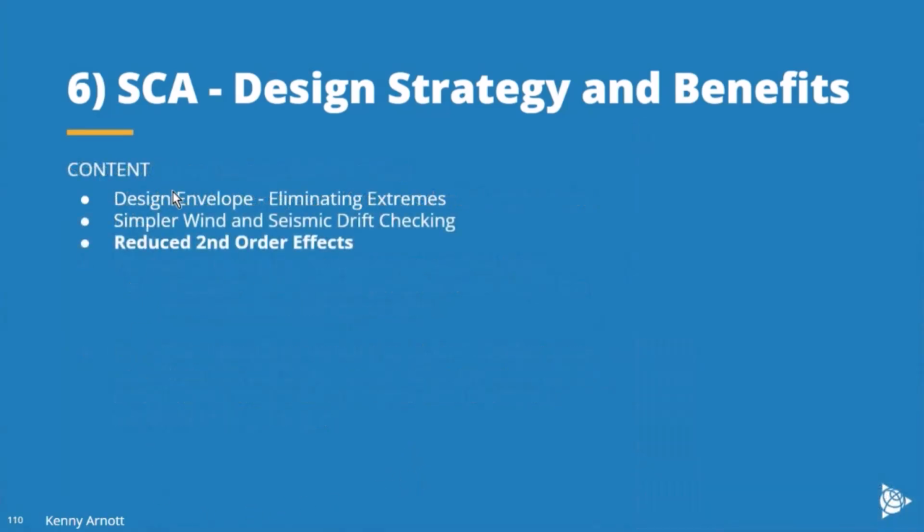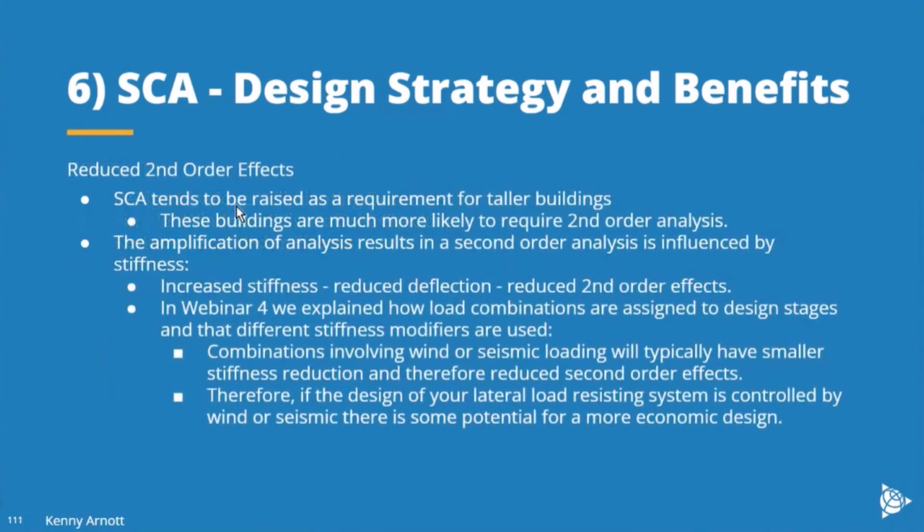And then the final part in here about the benefits is a potential for reduced second order effects. Stage construction analysis tends to be raised as a requirement for the taller buildings, and these buildings are more likely to be susceptible to significant second order effects. The amplification of analysis results is influenced by the stiffness. As you increase the stiffness, you reduce the deflection, and therefore you reduce the second order effects.